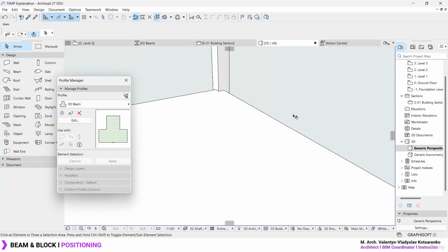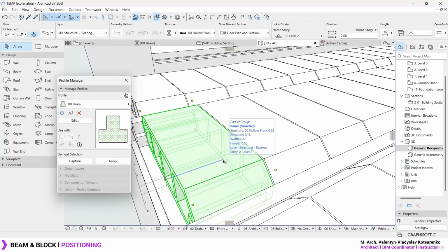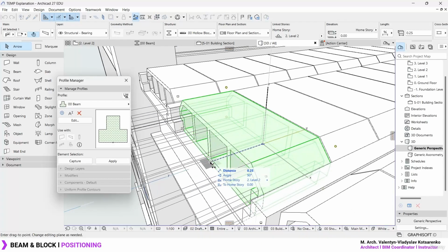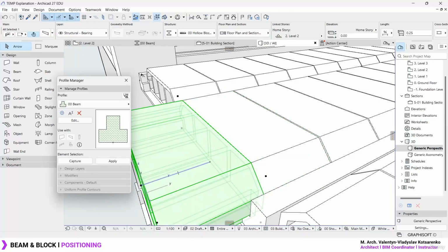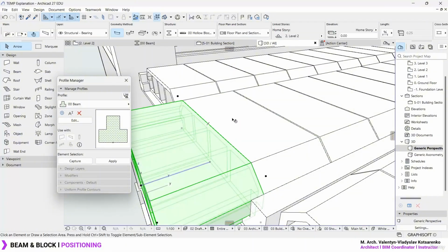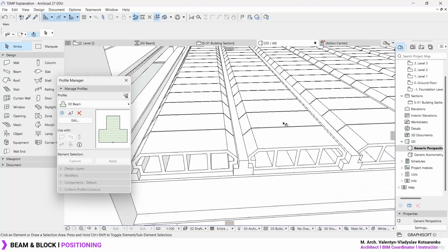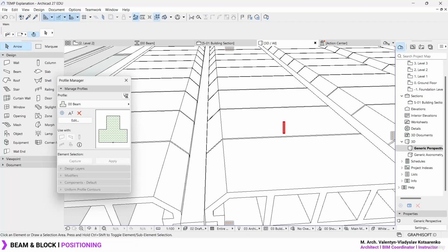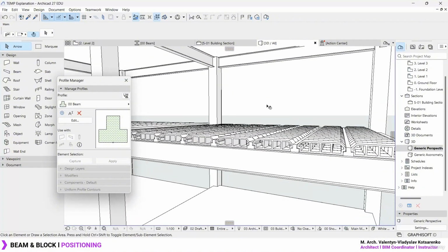And as a small tip that I'm going to share with you, if you want to create some type of joint separation or small separation over here, make sure that you never copy the hollow block exactly with the reference line touching the other reference line, because what is going to happen is it's going to delete the small separation gap over here, and it's going to look as a basic type of prefabricated element. So make sure to leave just a really tiny separation over here, 1 millimeter, 2 millimeters, something like this, in order for ArchiCAD to simulate this as best as possible.